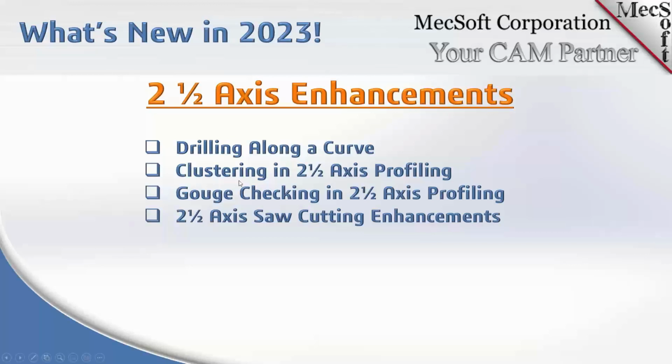And we also have a new clustering command or option parameter in 2.5-axis profiling. If you have multiple inside-outside cutouts of the same part, it will cluster those for you. And then we added gouge checking in 2.5-axis profiling. This comes in really handy if you have a lot of curves and they're not necessarily closed and maybe they overlap.